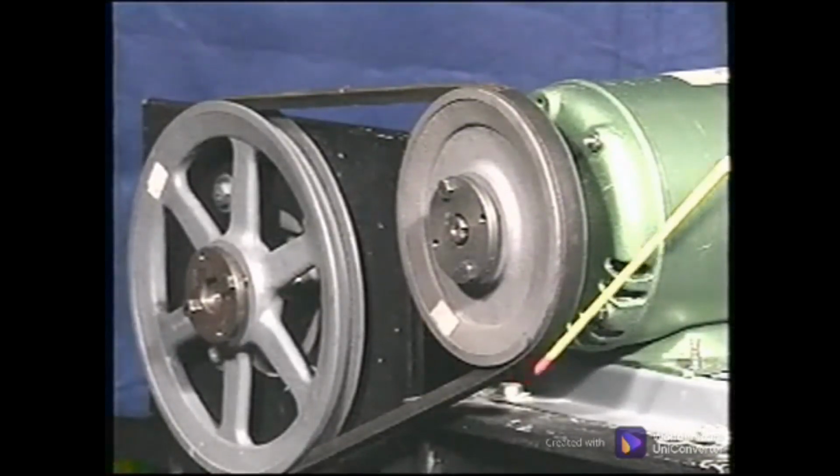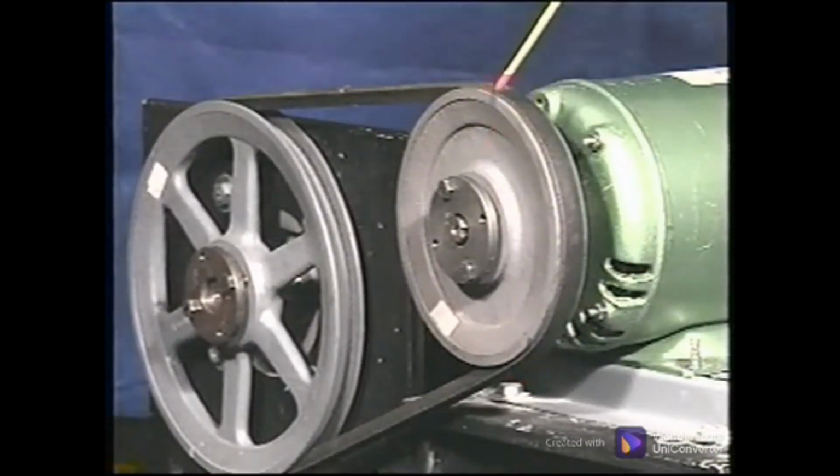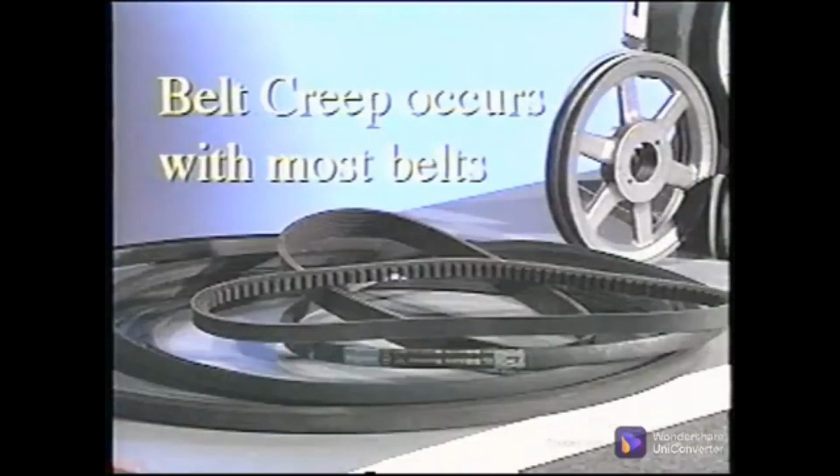This difference creates relative motion between the sheave and the belt, which is referred to as belt creep. It is present in most belts, except those which have internal cords that don't stretch, such as in the case of steel-corded belts. Even under the best conditions, belts slip, and in multiple belt drives, they slip and creep at different rates, generating excessive amounts of heat.